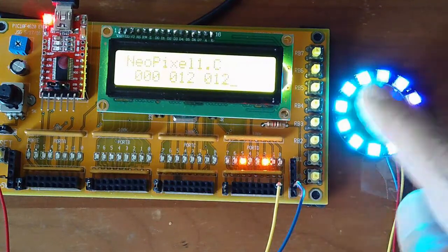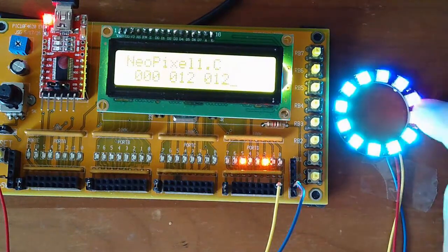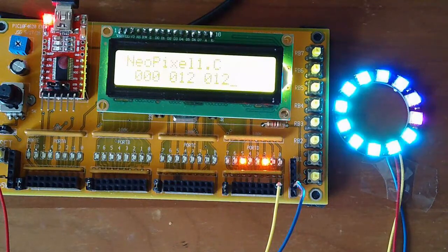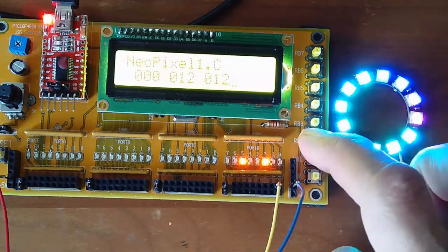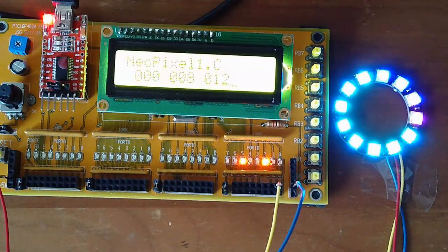And notice that only 8 of the lights are lit up. These last 4 are whatever they were last time I ran the NeoPixel. That was from NeoPixel 0, the rainbow pattern. If I only call it 8 times, the last 4 lights never see a bit pattern coming through. And so they just remember the old value. So that's the second code. I can sit there and vary the light levels. Again, it's kind of nice having the LCD display also, so I can see what this color corresponds to. This is 0, 8, and 12, where 255 is full brightness.